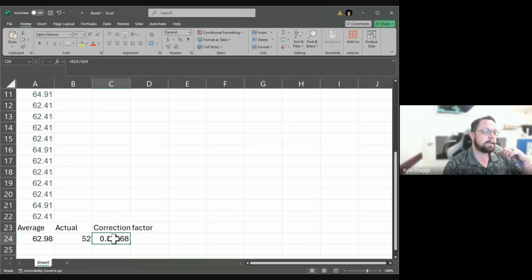What this means is it's overreading by something on the order of about 20%, but because sound pressure levels are non-linear, they are exponential in their behavior, that 20% off is a lot. So batch to batch, variation to variation, that particular factor is significantly off.